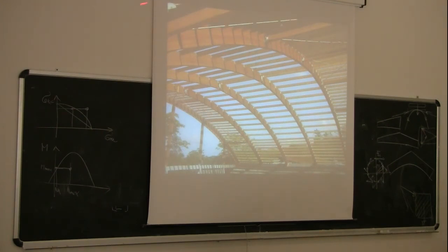So, a number of arches. You see three-pin arches, 1, 2, and 3. Some purlins. Those purlins, as you can see, are very small compared to the height of the arch, so they don't provide enough support in terms of lateral torsional buckling. In this case, we need to refer to this point here, where there is the bracing system.